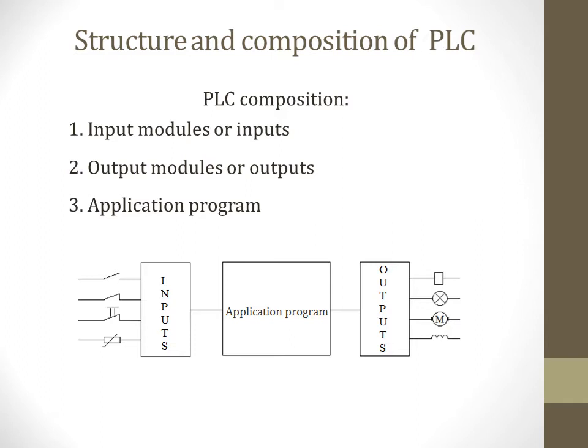In the input modules, we can connect any sensors or measuring devices or instruments, and by these inputs we can collect the information from the plant or control object. Then this collected information will be processed in the application program.